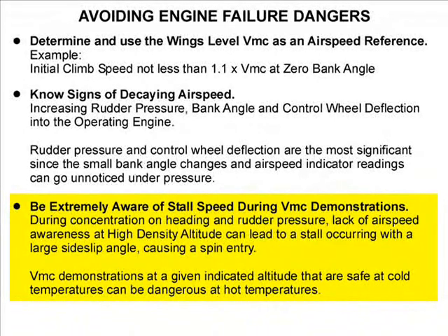During VMC demonstrations, it is extremely important to be aware of stall speed. While concentrating on heading and rudder pressure, lack of airspeed awareness at high-density altitude can lead to a stall occurring with a large side-slip angle, causing a spin entry. Remember that VMC demonstrations at a given indicated altitude that are safe at cold temperatures can be dangerous at hot temperatures.